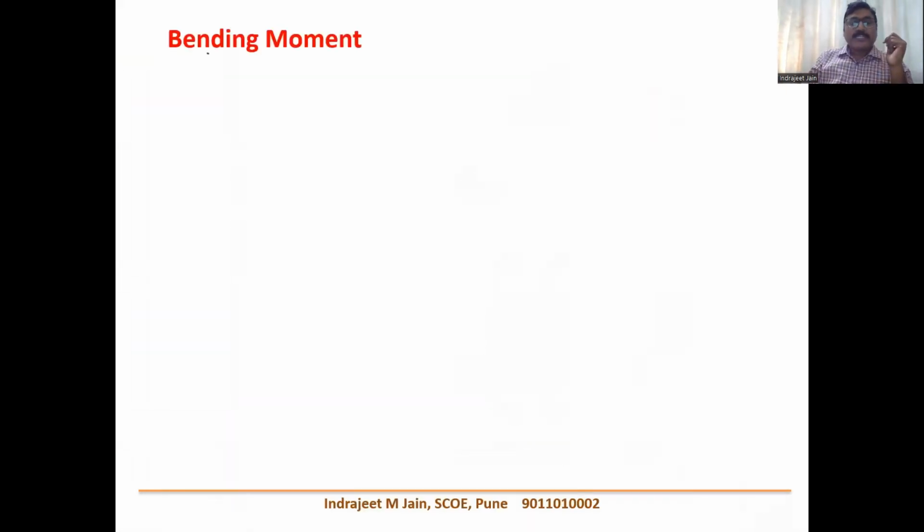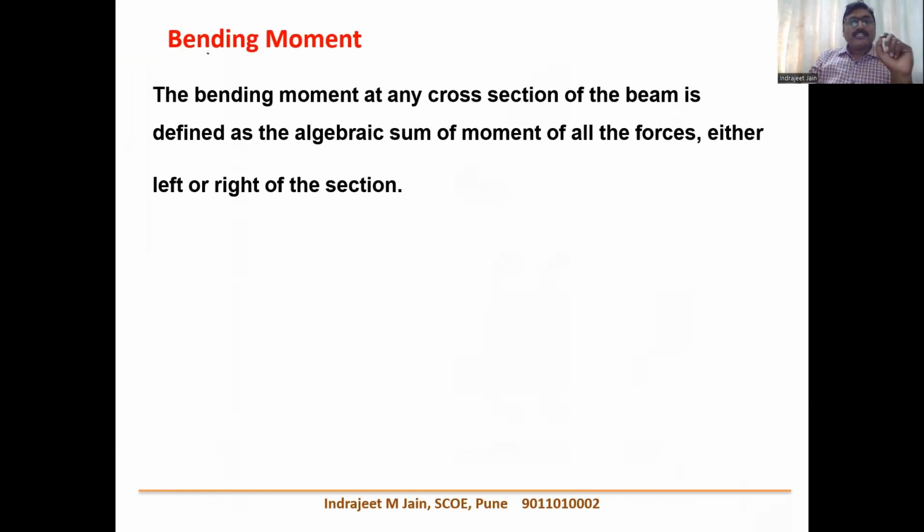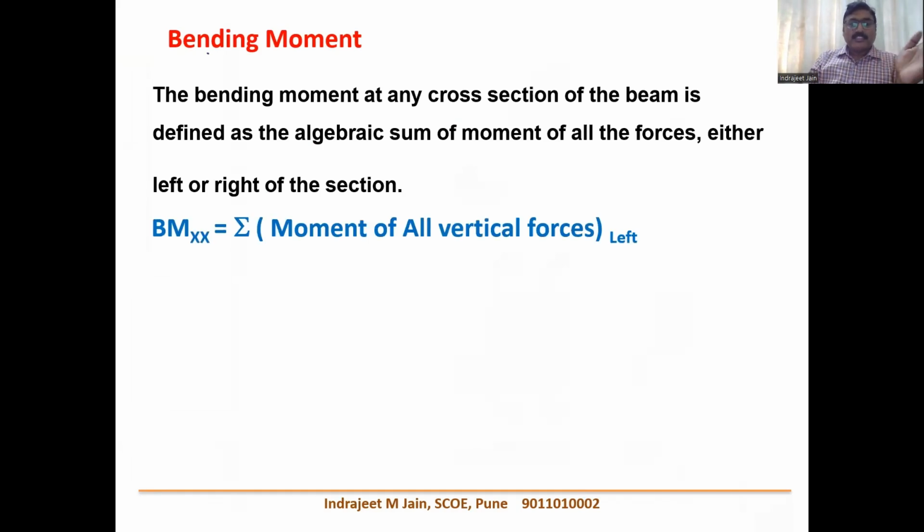Now, the next concept is bending moment. Bending moment again is the algebraic sum of all the moments of the forces either left or right of the section. So bending moment about any section xx is equal to the summation of moments of all forces either left or right of the section. So here we are considering the left of the section.